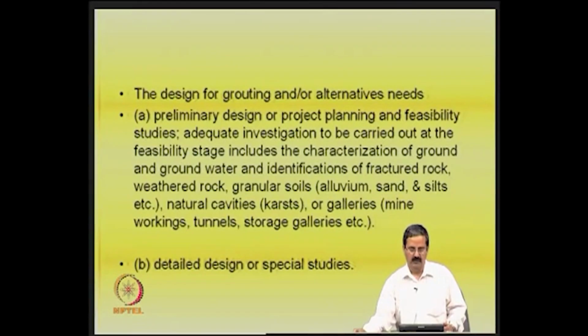You must be able to identify the type of grouting, the type of installation, the type of quality control you are going to have. One may even try a preliminary study on how it can be helpful in a small area and then extend it to a larger area, because you need to have experience with the technique. Once you have the experience, it is quite easy to adopt.